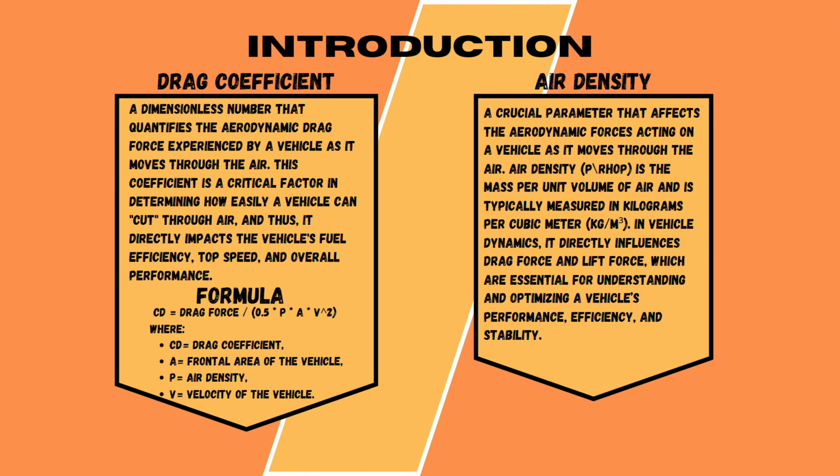The first one, drag coefficient, is a dimensionless number that quantifies the aerodynamic drag force experienced by a vehicle as it is moved through the air. This coefficient is a critical factor in determining how easily a vehicle can cut through air, and thus it directly impacts the vehicle's fuel efficiency, top speed, and overall performance.